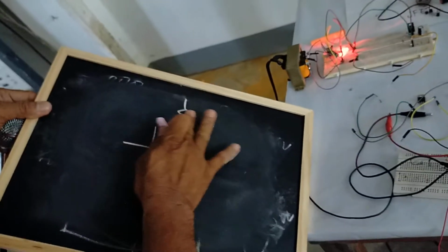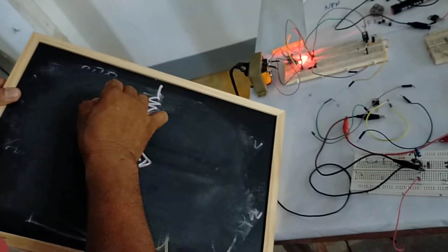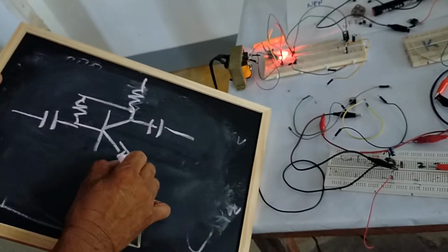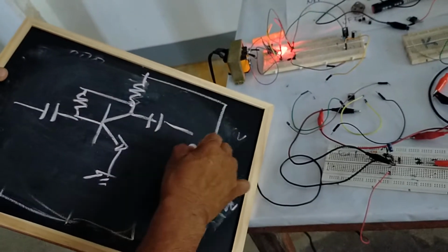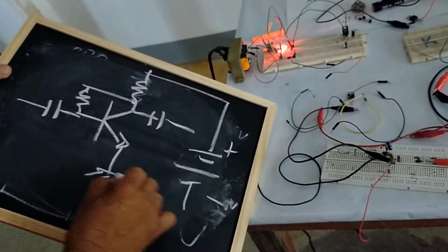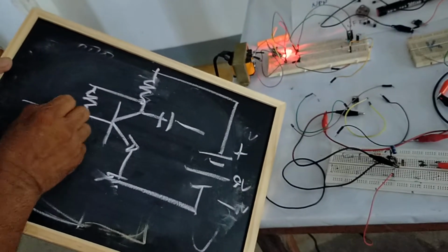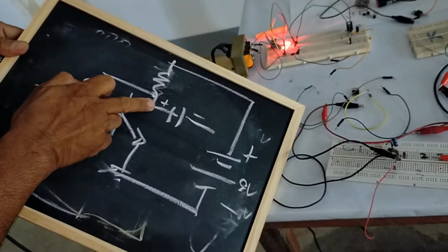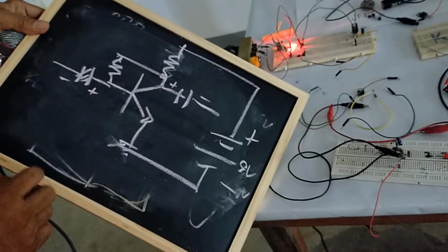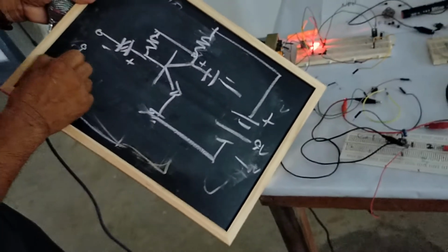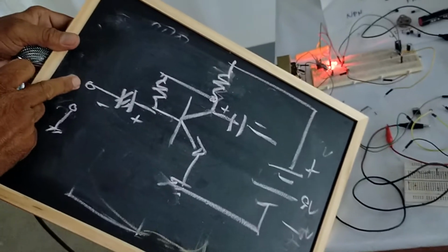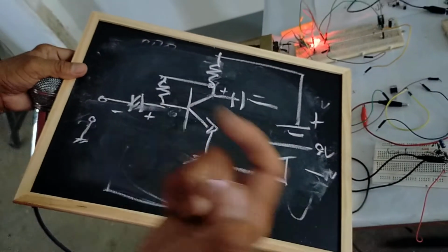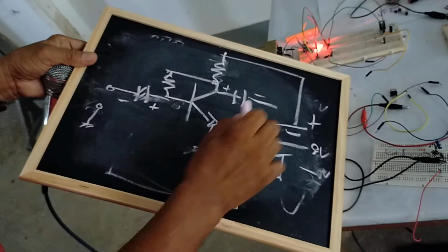We have here a resistor over here, and then we have here the capacitor. This is supplied with 9 volts. The 3 electrodes: emitter, base, collector, NPN type. This is now the input line. The AC signal or the sound signal is fed here to the base, and the output signal, which is the amplified or enlarged signal, is taken at the collector.